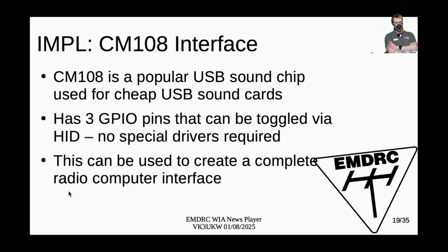Now the CM108 interface. CM108 is a popular, well, older chip now. There's probably not that many new products made with it, but you can get a lot of them for $15 on AliExpress as a fully implemented USB sound card. And the special thing with that chip is that it has GPIO pins, just pins connected to the chip that you can drive with a high level or a low level, and that you can also use as input pins.